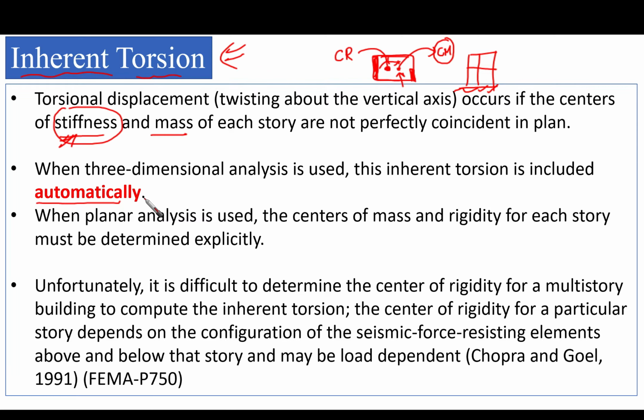However, whenever you are making planar analysis, the centers of mass and rigidity for each story must be determined explicitly. You need to work out the places of the center of mass and center of rigidity, and you need to find whether there is eccentricity there or not, and you are going to explicitly calculate it.